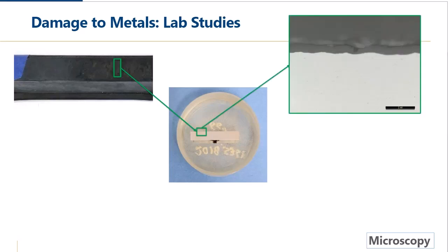And I'm sort of outlining the anodic layer in those squiggly yellow lines. And you can see with that one arrow in the center that there's a big old pit or this crevice in the anodic layer. It hasn't gone completely through in this area that's not severely degraded, but the anodic layer is barely there and isn't able to function as intended as a protective layer on the aluminum.